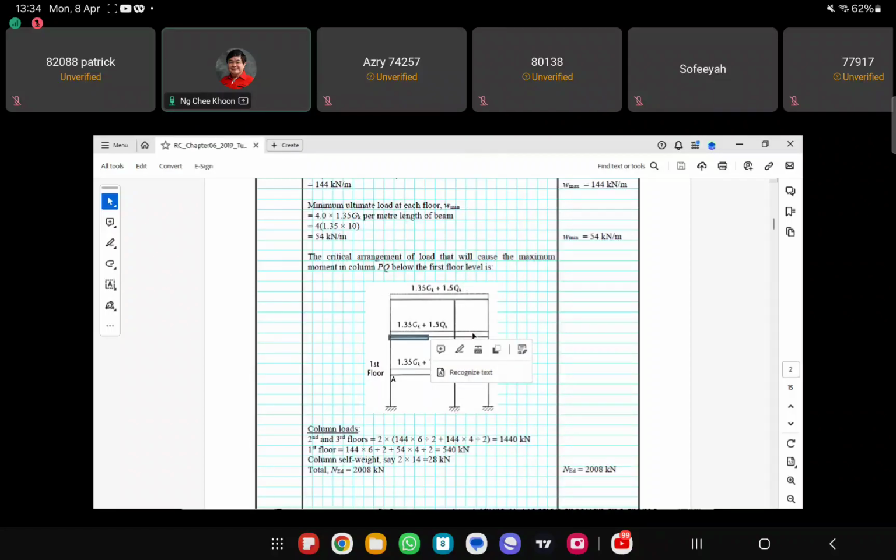And then this second floor is the same as the top floor here. That's why we multiply by 2, right? So 2 times this whole thing will be the load transferred from this floor plus this floor, right? So this load will be transferred here, and then you go down from this column, and plus this load, and then go down this column and transfer to this column, right?